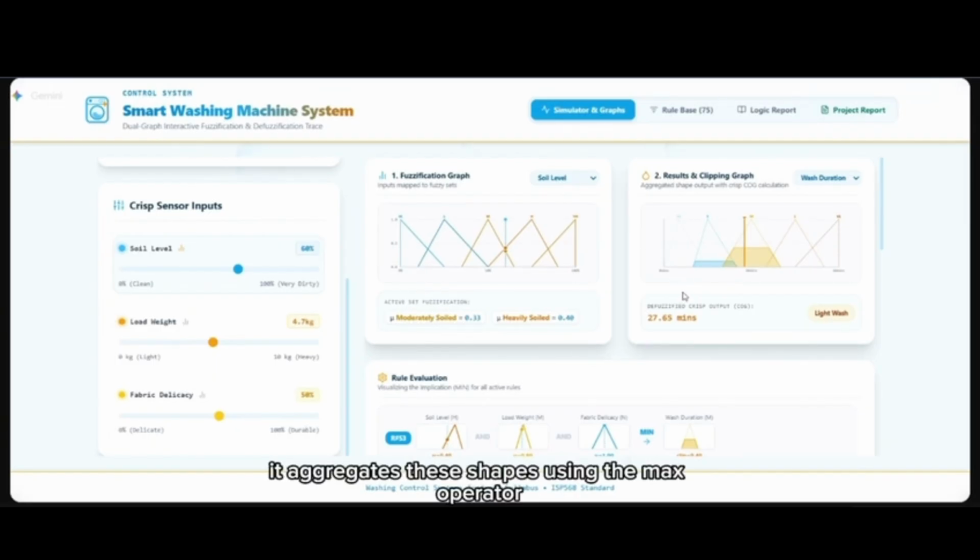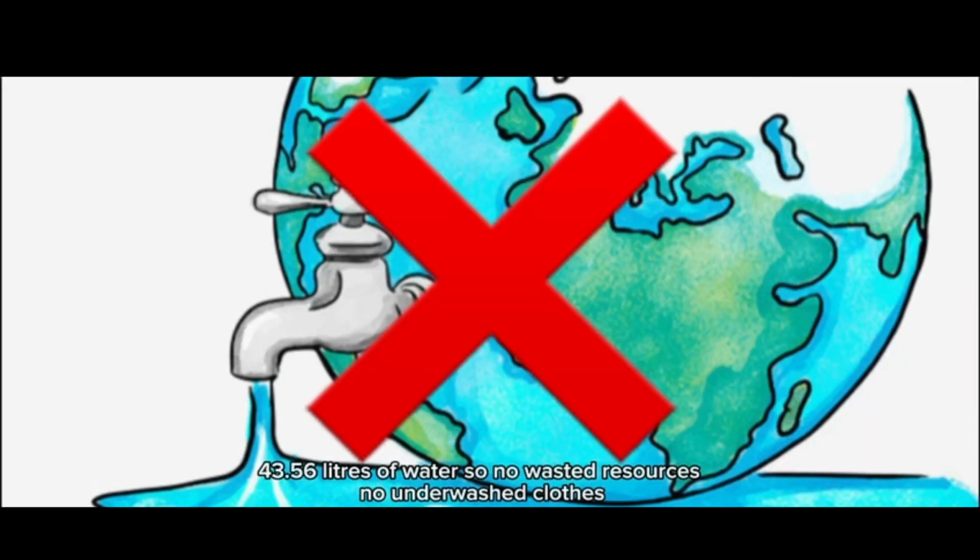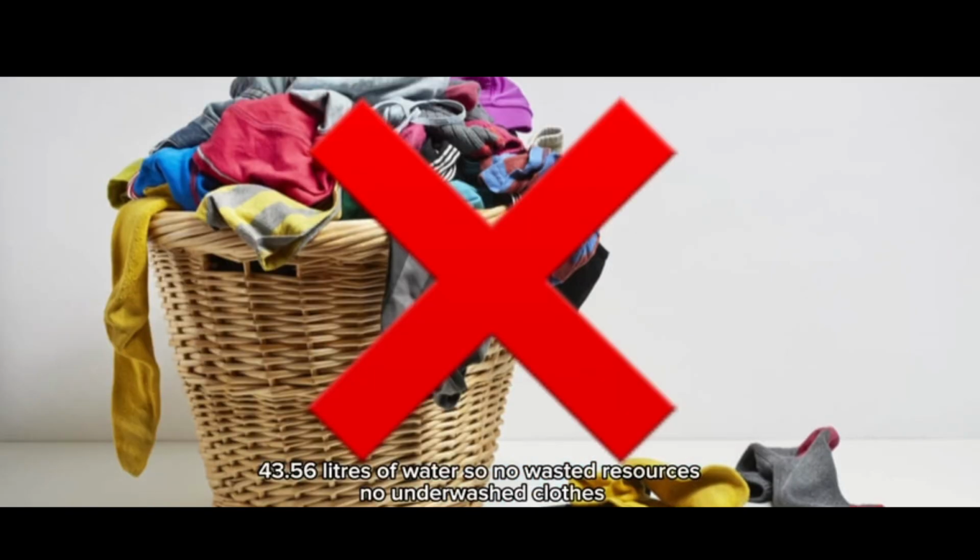It aggregates these shapes using the max operator. By calculating the center of gravity (COG) of this combined shape, the system defuzzifies the data into a precise real-world instruction. As a result, our live control output dictates exactly 27.65 minutes of wash time and 43.56 liters of water. So no wasted resources, no underwashed clothes.